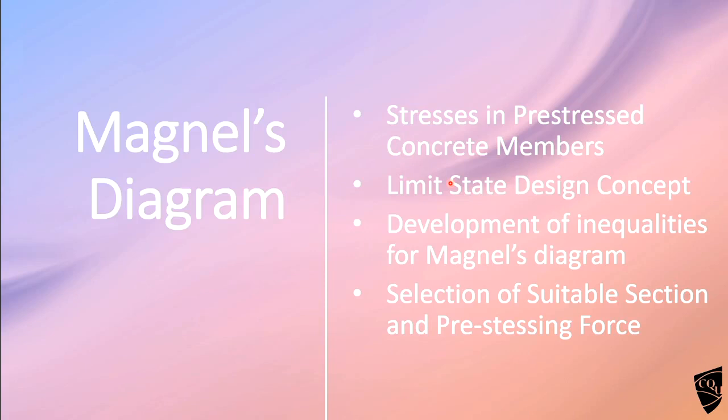If we want to develop a Magnel diagram, you should know what the stresses are in the pre-stressed concrete member, because Magnel diagrams use the stresses to develop that diagram.